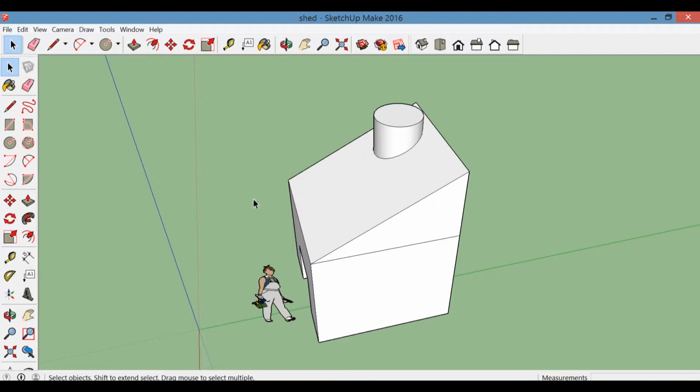If you ever forget the dimension of a part, you can use the tape measure tool and select the 2 points of the line you want to measure. Or alternatively, you can select the length of the side of a rectangle you want to measure, or the center of a circle to a point on its side, etc. And the dimension will be displayed on the same white rectangle in the bottom right corner that displays your other dimensions. Of course, we always use lines as an example, but keep in mind that as you play around with this tool, you're going to find that the tape measure tool allows you to measure things like rectangles, circles, lengths, and even distances between two different objects.